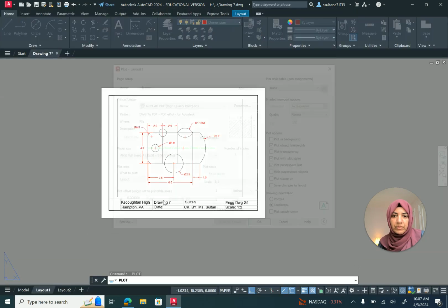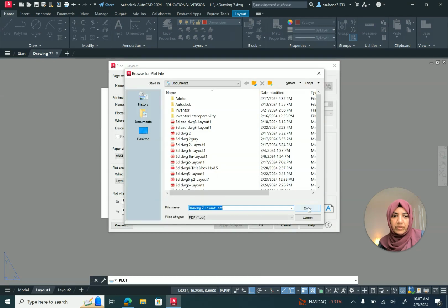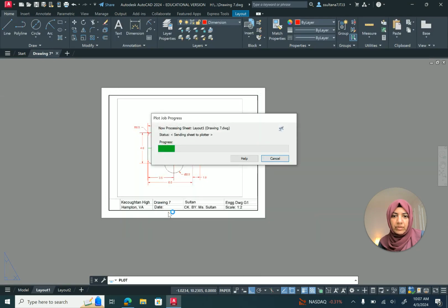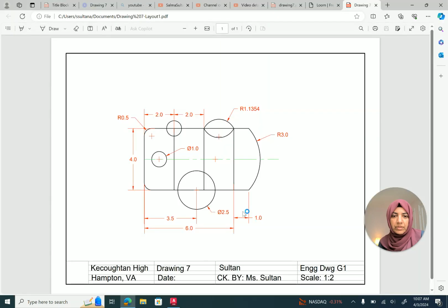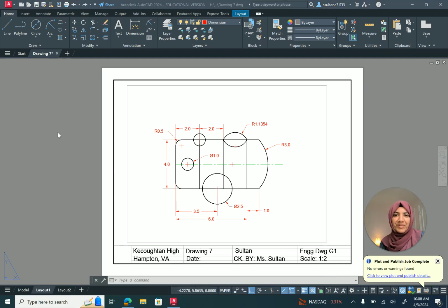And meanwhile update your title block including the title of the drawing and date and the scale. Select your viewport and adjust the scale. So I had mine 1:2, and that completes the drawing.